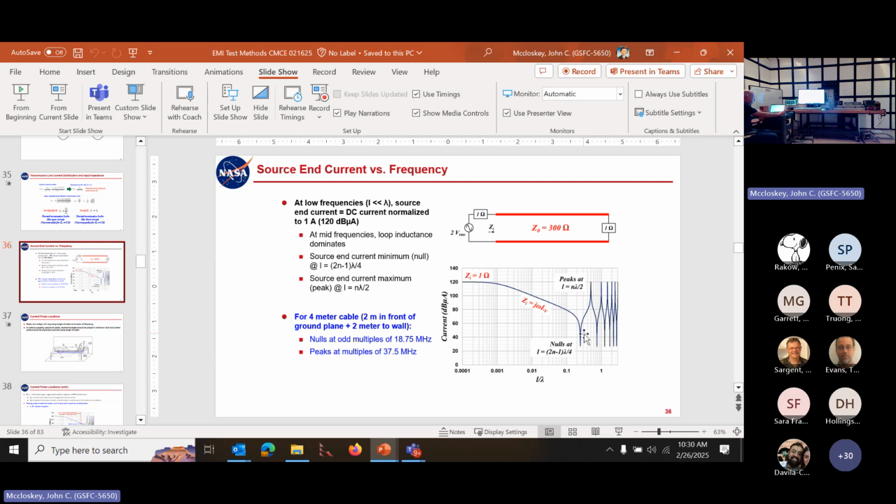You can see that, I have nothing there. I'm fine. You could have, you see with these power converters without any filtering, it's got junk going up to pretty high frequencies. The cable layout could basically be masking a potential problem, and you're pretty much defeating the purpose of the test.